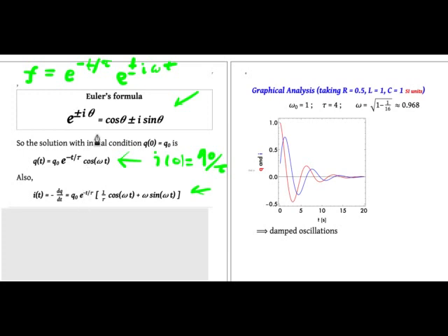When t goes to infinity, q will just go to 0, and I will go to 0. So that's the kind of steady state. After I close the switch, after a long time, the capacitor will have no charge, and the current will go to 0. So both of these functions will approach 0 in the steady state. But starting from the initial condition, they approach that steady state solution exponentially. Those are called the exponential transients.